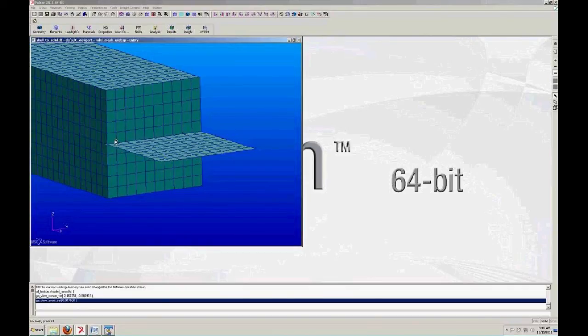So if you, for instance, refined the mesh around this joint, and then put a skin of surface elements just along here and here, you might actually get a good answer. Where I disagree, where I think it might be a bad idea, is some customers will basically put the shell elements inside the solid here. That will also get the model to run.